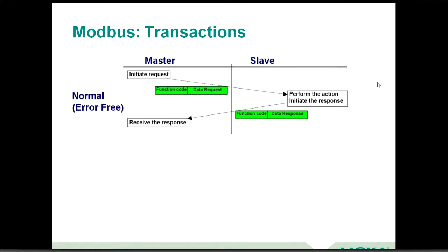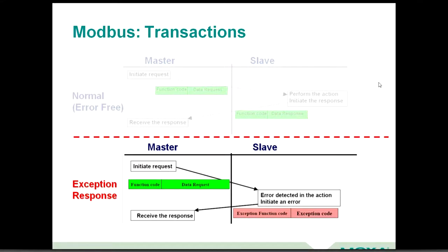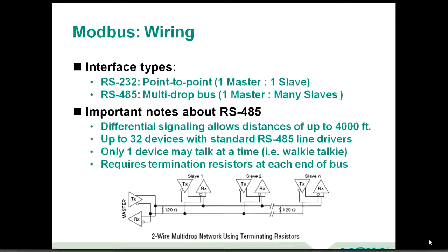Now there can be a problem where you might have a mistake with that, and in the case of maybe a configuration error, maybe you're sending a request to this slave that's not supported by that specific device. In that case, the device may respond back with an error code. And you typically see this from your Modbus Master or your SCADA system or your programming software for your PLC, where you'll get an exception code on this. So that's one of the nice things that Modbus has, the ability to handle these types of exceptions and do that within your application.